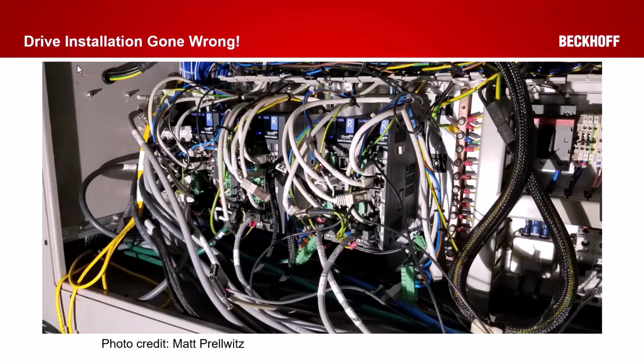And I looked and I looked, and I was like, where do we start? How do we know which cable is the right cable that's connected back to the PC? So we had to spend a lot of time looking at it. We found that the drives weren't plugged in properly. We saw that the cable that was unplugged was actually the communication cable, and some of the cables were looped back onto the other cables, and some of the 24 volts was miswired, and a lot of time spent just trying to communicate to the drives. This is why we do what we do.